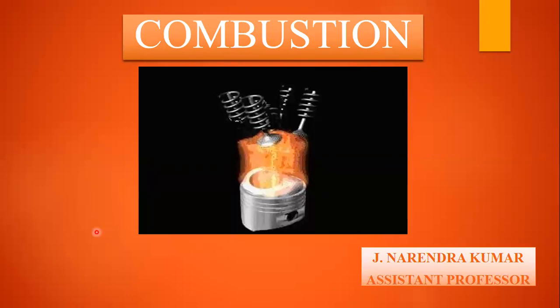If the pressure and temperature are maximum, then we have chances of getting complete combustion. Otherwise, if the spark is too early, around 40 to 50 degrees before TDC, then also we are going to have losses. So we need to follow some optimum condition for spark ignition.